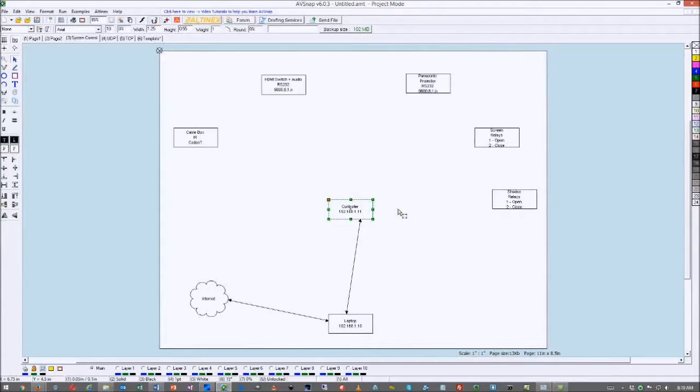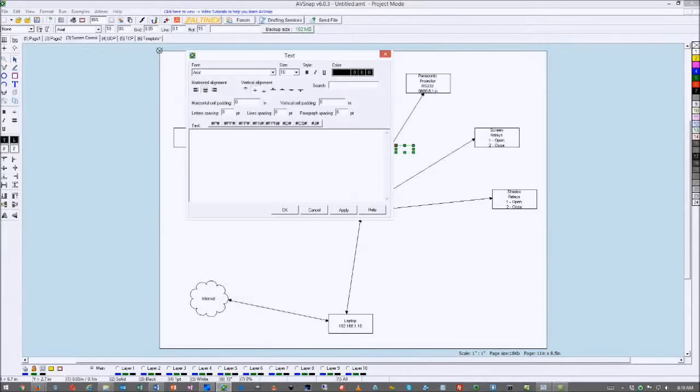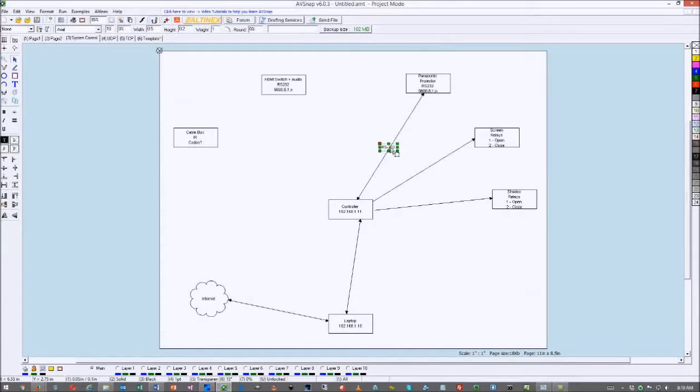And now I'm going to decide what I'm going to do. So here I'm going to do relay. This is going to be relay, so I'm going to need 2 relays. I'm going to need 1 RS-232. So that's bidirectional, and right away put a text here, RS-232, so I know what the cable is going to look like later. And you see how it's overlapped, so I'm going to put white fill, and then connect another RS-232, so that's going to be just a copy-paste.